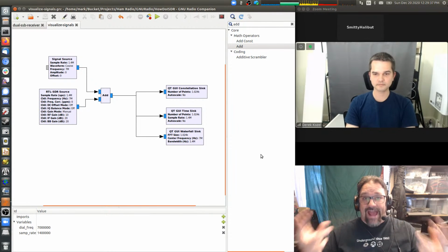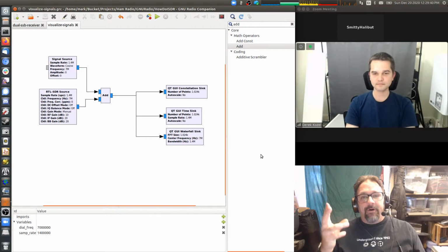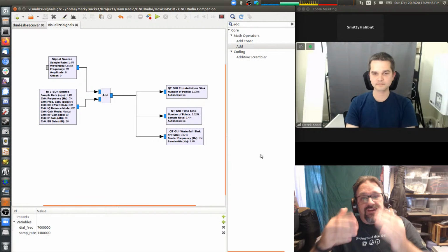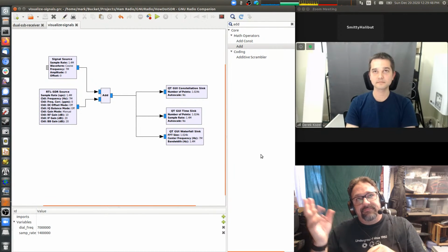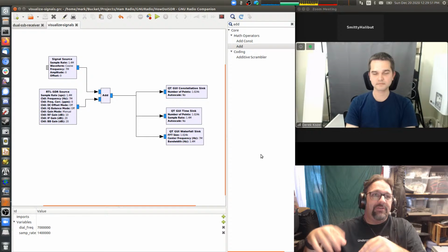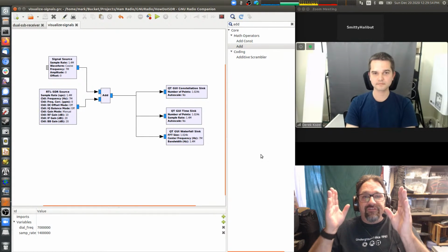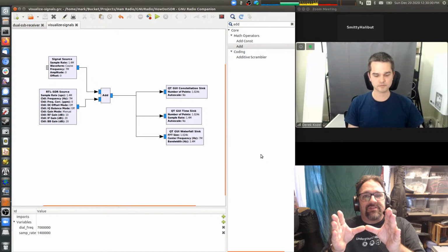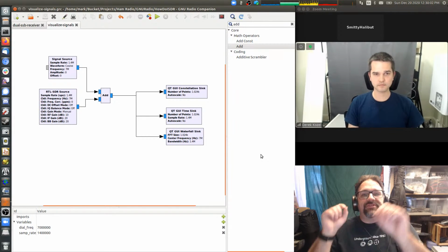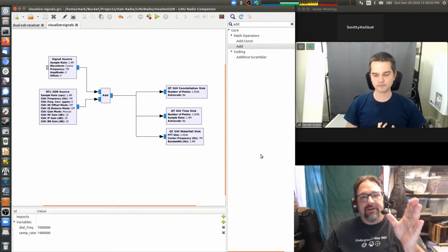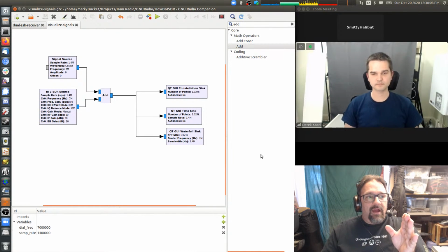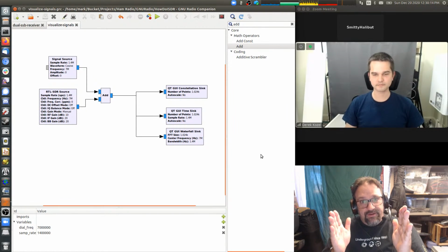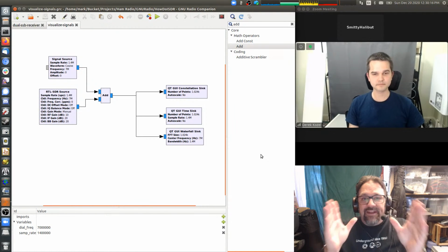right? I understand that. I also understand how I can take a block of that, feed it through an algorithm called an FFT, or a discrete Fourier transform, which is usually implemented using the fast Fourier transform. Anyway, you do a Fourier analysis on that, and that block of signal becomes a series of amplitude values for each of the frequencies that are represented in that block. And that is not a time series anymore. That is a frequency series, right? And so I get that.